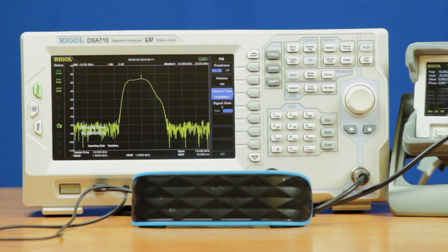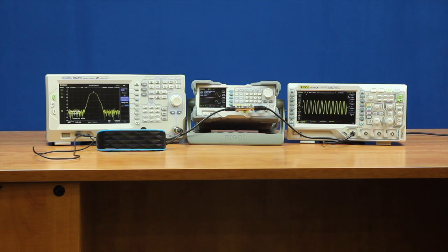But again, a great reason why FM works really great for this sort of application is because whether you have cables connected like this or antennas, the frequency changes are easy to pick up. Whereas with amplitude, obstructions, range, buildings, things like that can cause the amplitude to fluctuate, whereas the frequency tends to be more steady. So there's a great example of a simple FM external modulation into our spectrum analyzer using audio.